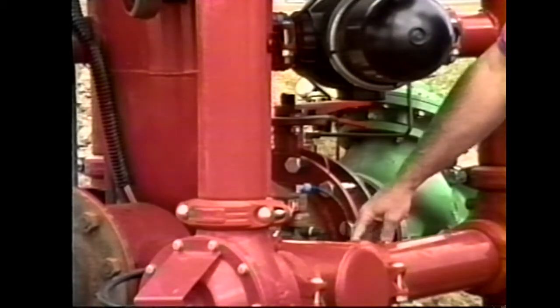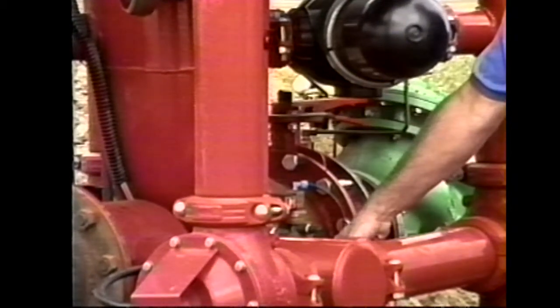A small 1-inch manually cleaned filter is located behind the pipes here. It is needed to clean the water for the hydraulic actuator for the disc barrels during backflushing. If the filter does not backflush properly, the problem often lies with this dirty 1-inch filter.